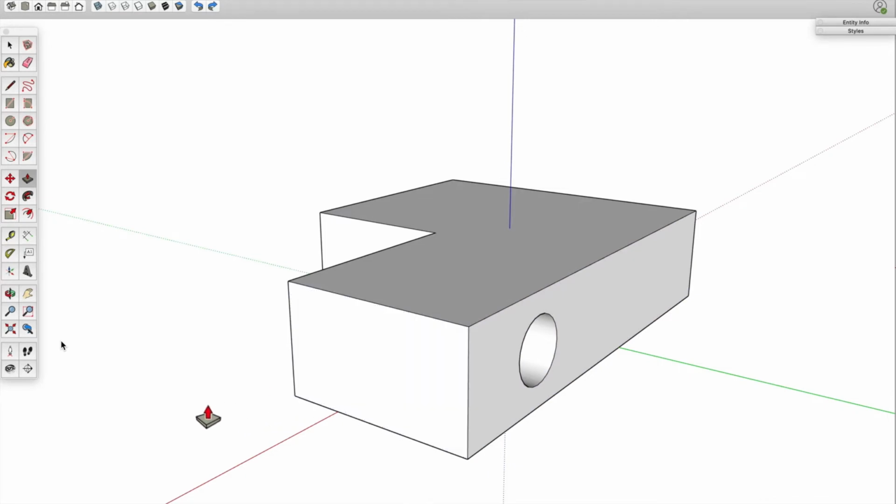So the first way was perfectly fine, where we just inferred this top point, and in some ways it was quicker, but you'll find that as you do more complex things in SketchUp, sometimes it's really good to see exactly what you're doing. Being able to use the mouse in this way, where you start an operation like the push-pull, and then you use your mouse to orbit around and then complete the operation, is only available because we use the navigation tools in the mouse. We use that 3-button scroll wheel mouse, and we use the mouse the right way, where we click, let go, move the mouse, and then click and let go to finish.